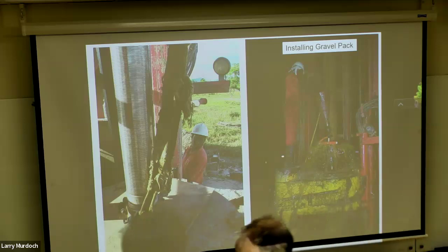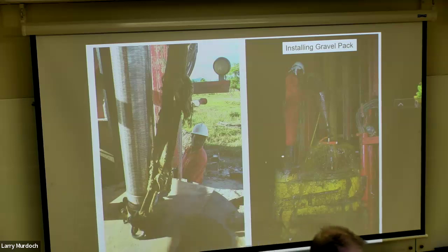Take a look at that. Here's another one of these flush joint threads with an O-ring in place, and this is just about 1 foot long, but you can see that these slots are cut over the full length. That's another example. So one way to cut the slots is with the circular saw that goes down and cuts. This is basically a piece of pipe where these slots are cut with a circular saw. Another way of doing this,